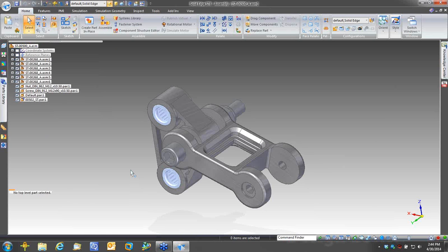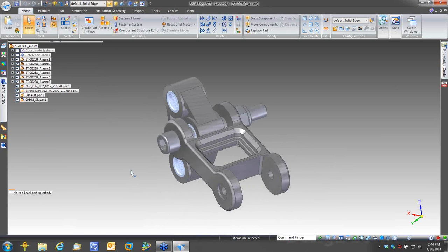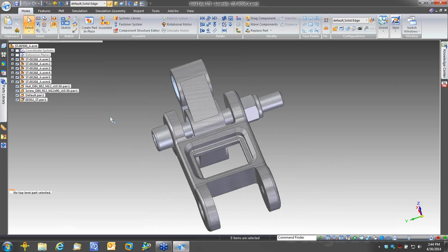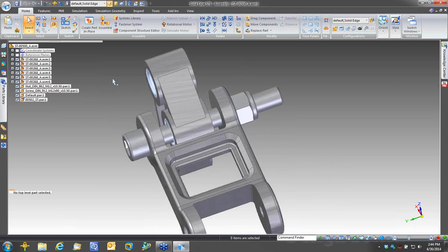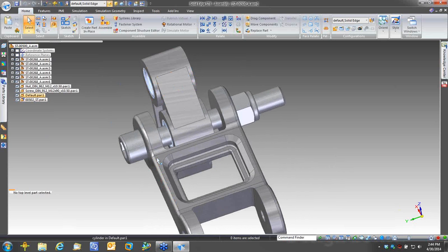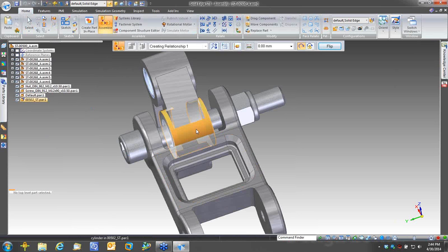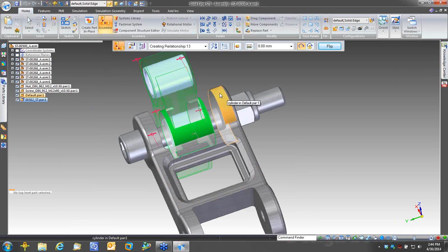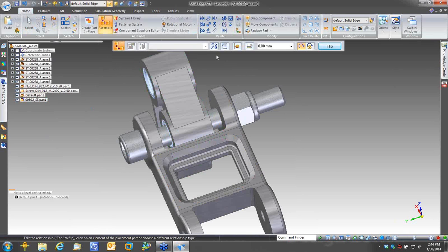You can also, as the designer, go through and make these same changes manually. So let's say I want to connect the housing to our arm. And what I can do is with our assemble tool say, well, let's make sure that the boss here stays aligned with the boss and the arm.